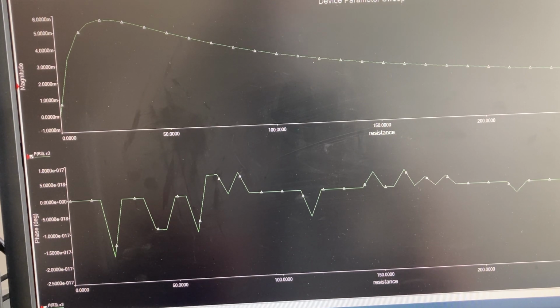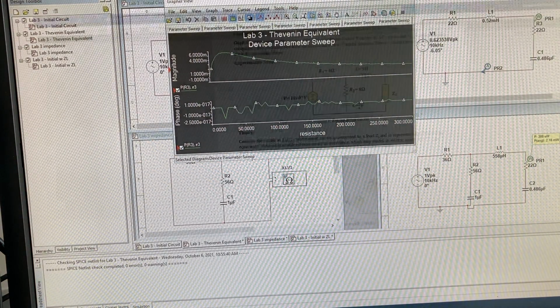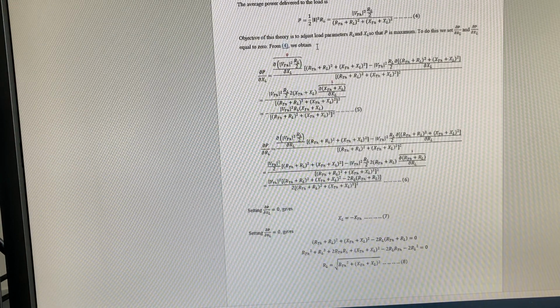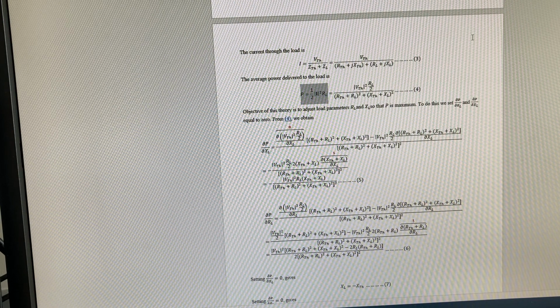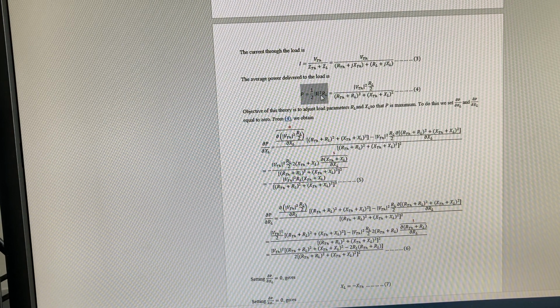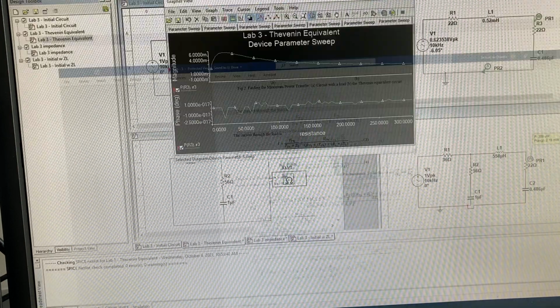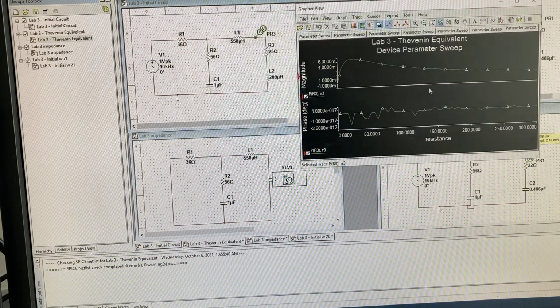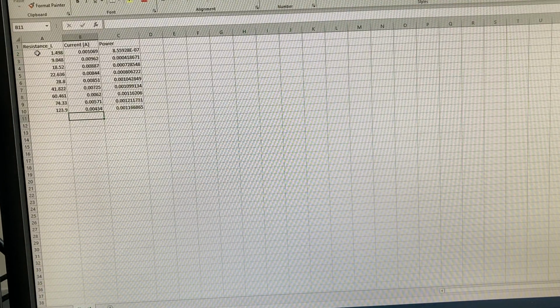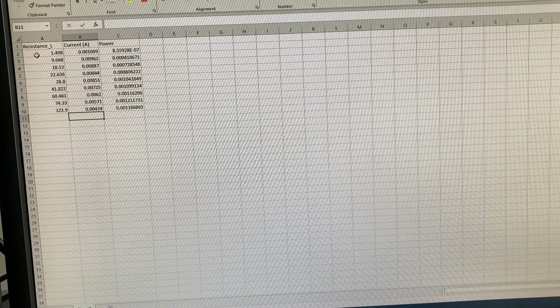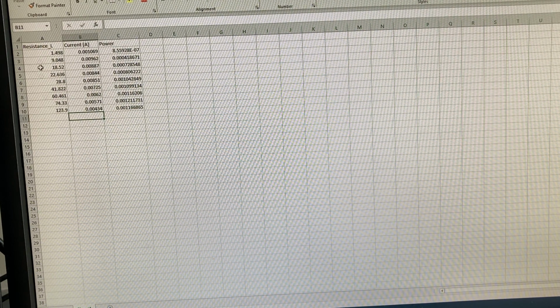And it's doing so according to this equation here. It's 1/2 I squared RL. So as you modify this RL value, this is a nonlinear equation, so you see a rise and fall. And that's what we get here. Hopefully when we plot this, as we change the resistance value of our load, we go from low to high, we should see something similar.